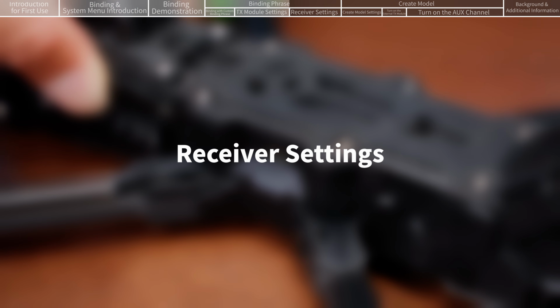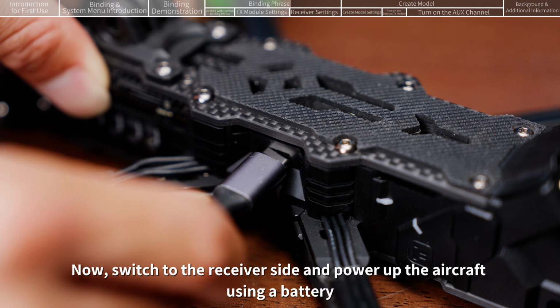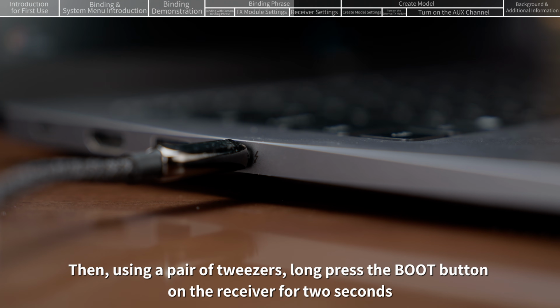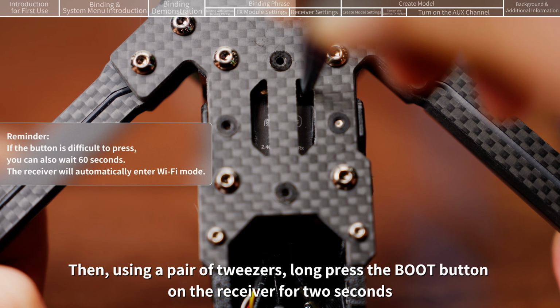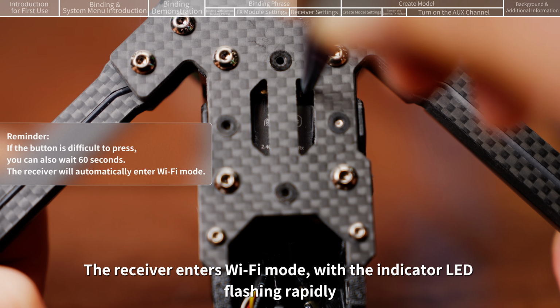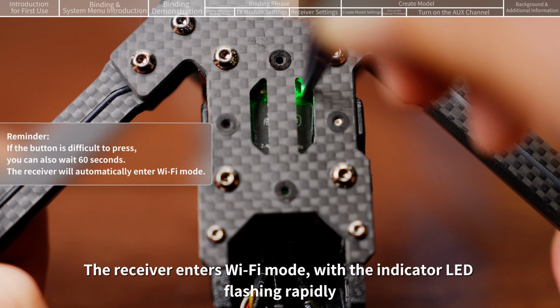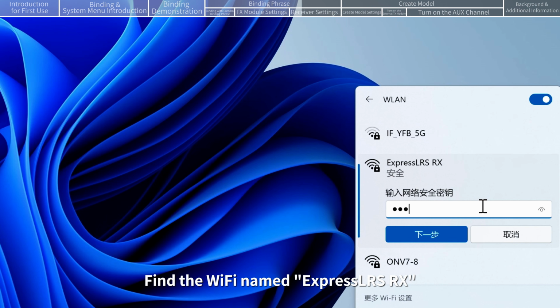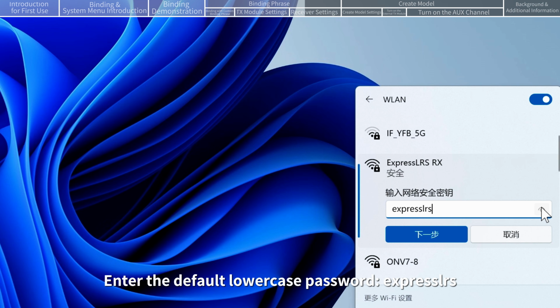Receiver Settings. Now, switch to the receiver side and power up the aircraft using a battery. Then, using a pair of tweezers, long press the boot button on the receiver for 2 seconds. The receiver enters Wi-Fi mode, with the indicator LED flashing rapidly. Then turn on the Wi-Fi option on the electronic device. Find the Wi-Fi named Express ELRS RX. Enter the default lowercase password, expresslrs.